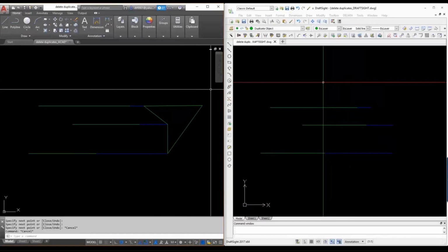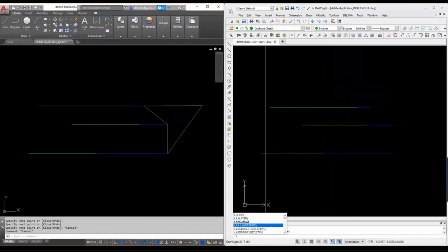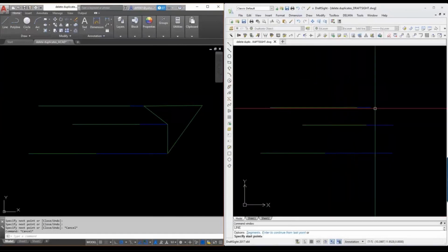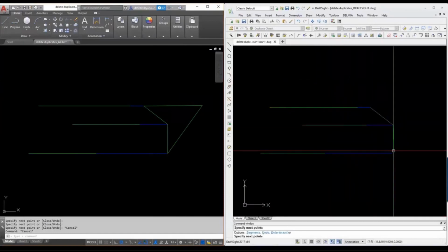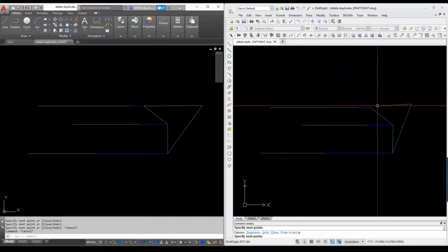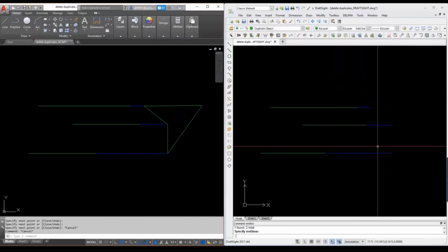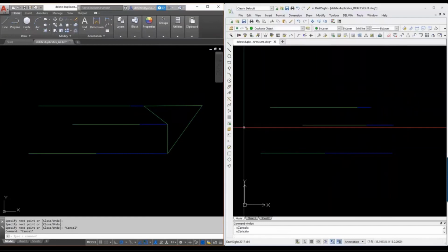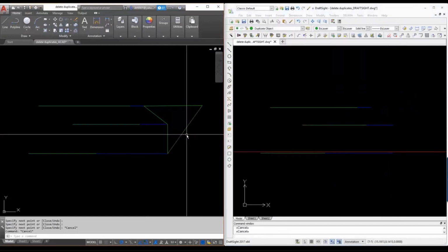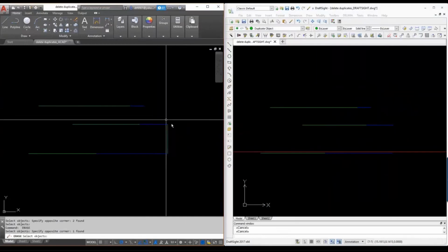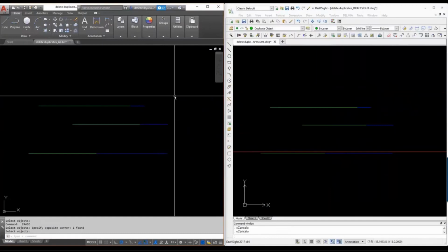Now I jump to the right side of the DraftSight. I type in L. Okay, notice how it filters as well. So it filters to line. So I'm just gonna click and draw lines as well. Okay, and then I have a right click where I can cancel and do things just like I did on the AutoCAD side. Okay, I'm gonna go ahead and select those and delete them just like I would when I'm over here on the AutoCAD side. So I can click erase, or I can pre-select them or hit delete, whatever I'm doing here. Very similar to what we're doing here.